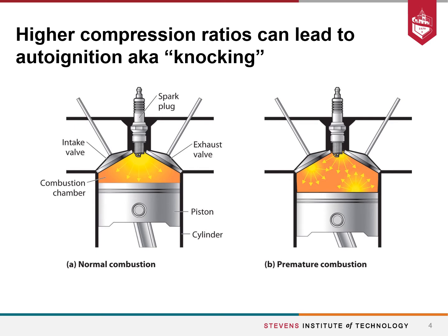If instead we look at the image on the right, this is premature combustion, auto-ignition, or knocking as we've come to call it. What happens here is we've compressed the fuel and air so much that its temperature has gone up and it has gone above the ignition temperature. So it auto-ignites, it spontaneously starts to burn because we've compressed it too hard. This is a problem because now the process is more random, it's not controlled, we don't know exactly what's going to happen, and it can damage the engine and cause losses in power and efficiency.